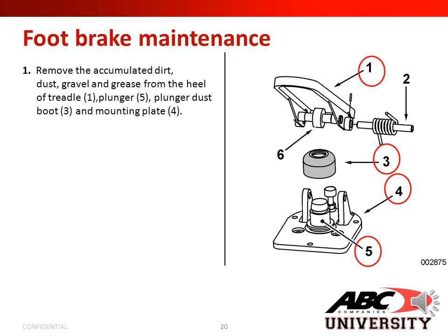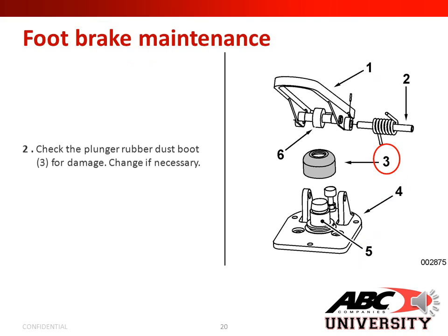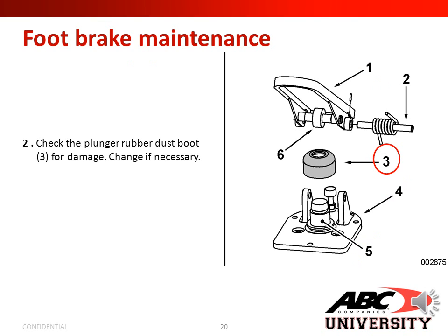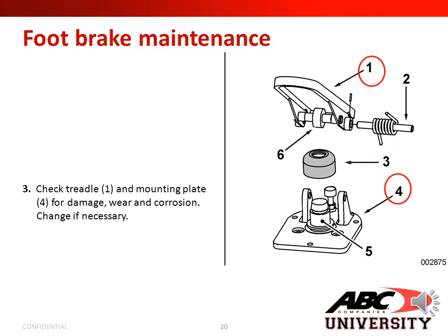First, remove the accumulated dirt, dust, gravel, and grease from the heel of the treadle, number 1, plunger, number 5, plunger dust boot, number 3, and the mounting plate, number 4. Next, check the plunger rubber dust boot, number 3, for damage. Change if necessary. Step 3. Check treadle, number 1, with the mounting plate, number 4, for damage, wear, and corrosion. Change if necessary.